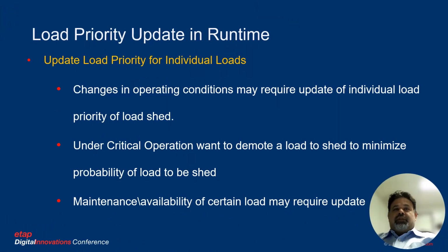And another feature that has been added that I believe is critical is the capability of updating the priorities of loads individually in runtime without having to bring the system offline. This capability gives the operator the power to switch the priority of a load depending on specific conditions that may not have been taken into account while setting up the load shed condition.